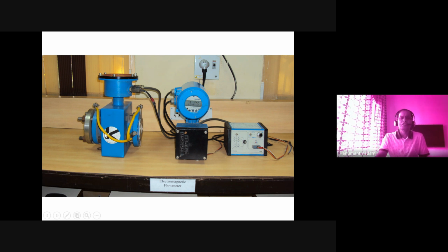This simulator is required for testing purposes of the electrode. One side it is closed and it is filled with full water, and whether the electrode is sensing the zero, that is tested. So the electrode is tested. If it is not, then the electrode is replaced, or any wiring damage inside it will be rectified. And for the actual full range, suppose there is a 100 liters per hour range, it is tested on the flow setup, where actual tanks are there, calibrated tanks, we can say. So in 1 hour 100 liters comes down from the tank, then in another tank it is showing 100 liters there, then whether the meter shows the same. So it is like physically we are checking it.